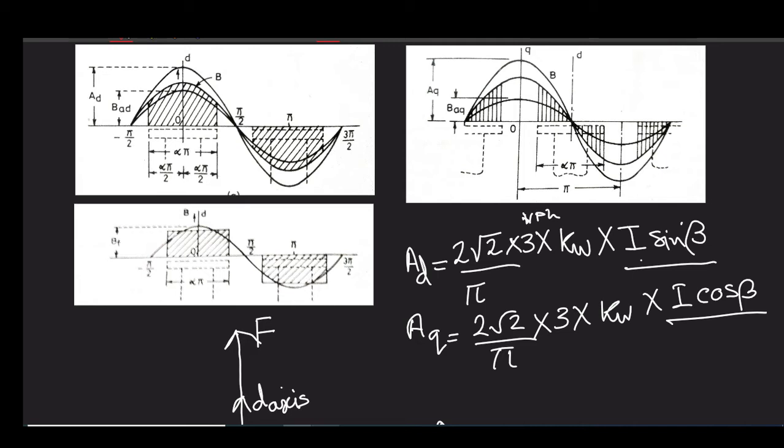basically it is obviously the MMF, but at the same time, in case of variable reluctance, it would be better to say that it is the flux density that makes the impact, not the actual MMF, rather the flux density with which things are proportional. Now, for these two different flux densities, like BAD and BAQ, you can expect two different values of EMF induced.